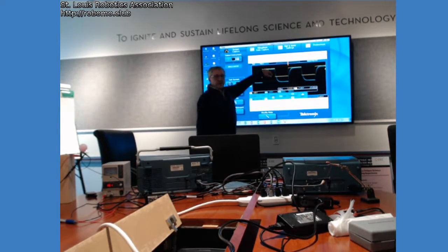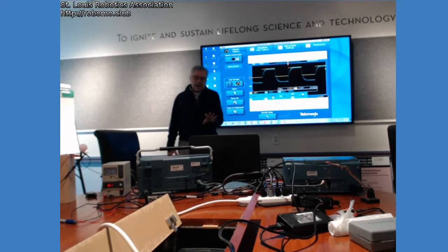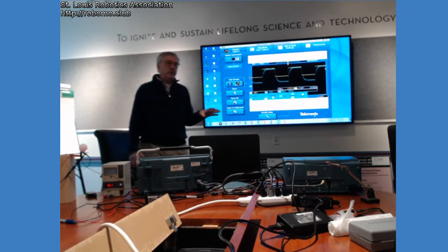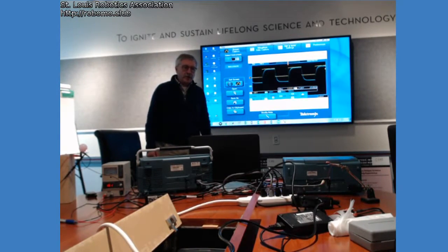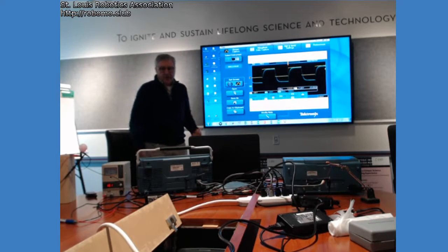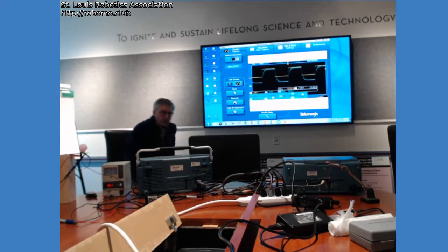Now we're in the region where you want to be careful, because 6 volts is exceeding what your Arduino is capable of. You wouldn't want a 6-volt signal coming into your Arduino, but you could bias it for 5 volts like we had before. So let's try it.